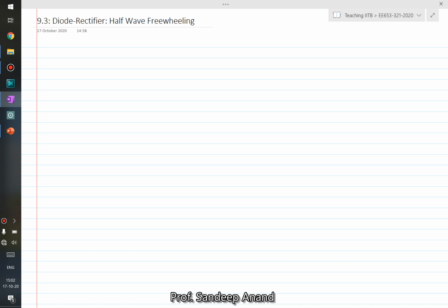So the half-wave rectifier that we were discussing looked something like this: a single-phase half-wave, single pulse rectifier. And then at the output you can have a load, which we saw, for instance, in a DC machine, you can have some inductance, some resistance, and a voltage source, the back EMF. So it could be an RLE load. This is the diode, this is the input voltage V in.